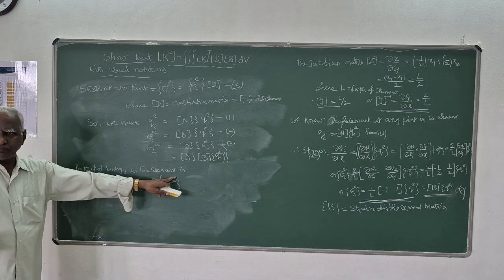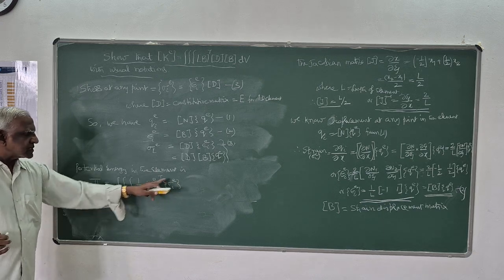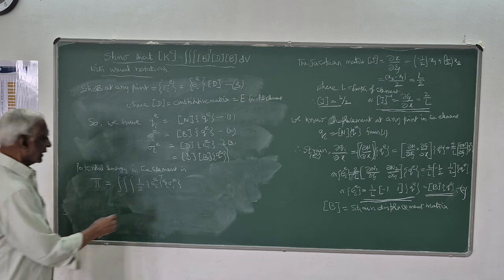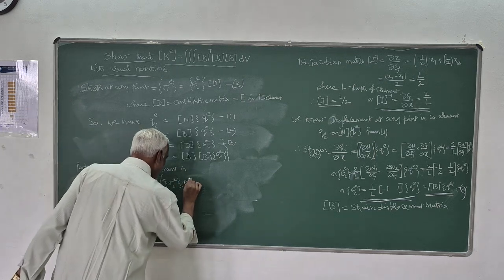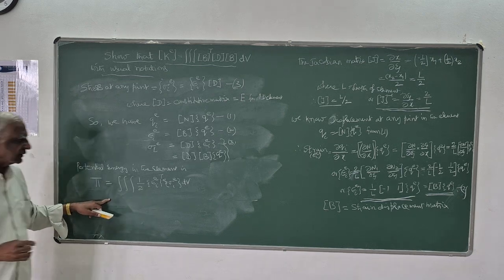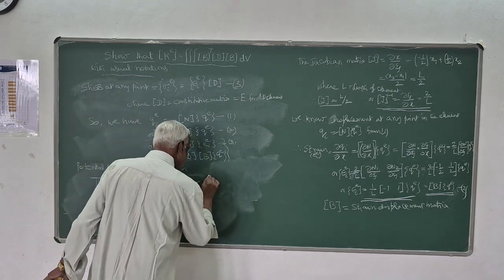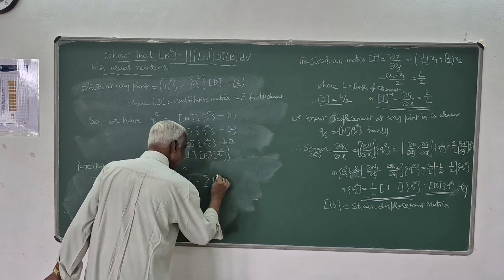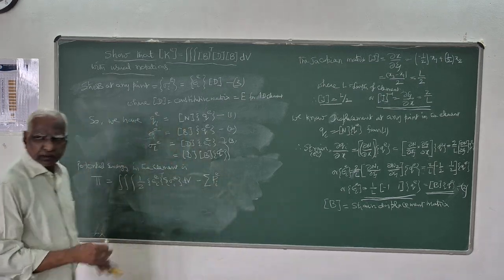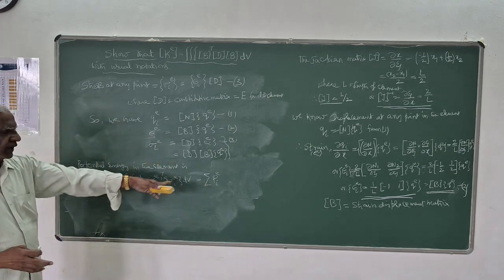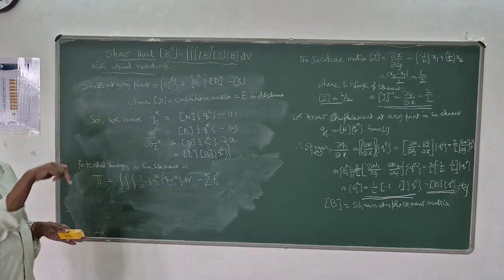That's why when we are multiplying matrices of same order, I have to write one transpose of the other. So into dV, this is the internal strain energy, minus the external work done, that is Pi of the element nodal loads, because all loads we have to treat only acting at the nodal points.